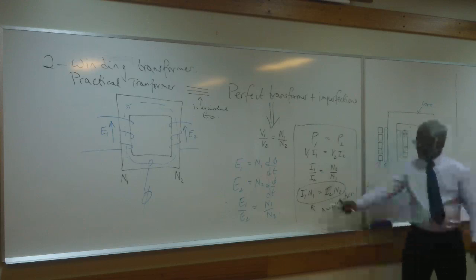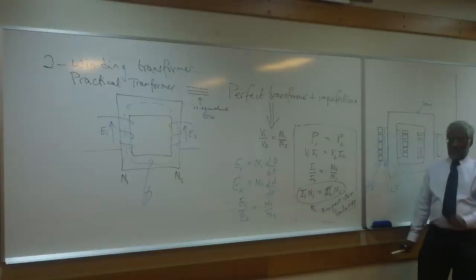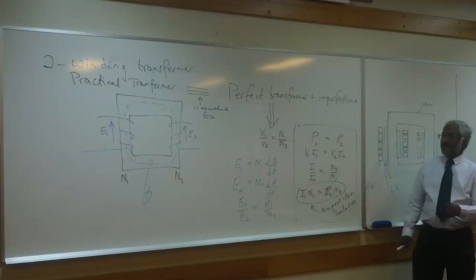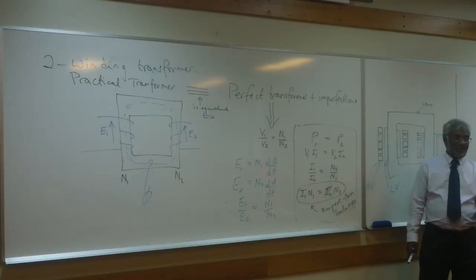Ampere turn balance, because this is ampere, this is turns, the product, they are balanced. That's for a two-winding transformer. You can extend those equations to a multi-winding transformer.